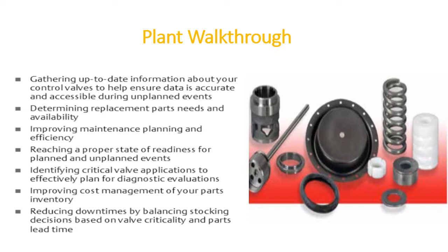Either you can do it manually, or you can maintain one Excel sheet, or you can tabulate the data and feed it into your SAP system or CMMS system, where by just entering the equipment tag or the valve tag, you can access all the data about the valve. By data I mean you should have the make and model number of the valve and the actuator. Also, the serial number of the valves is often required by the OEM at the time of the spare procurement.